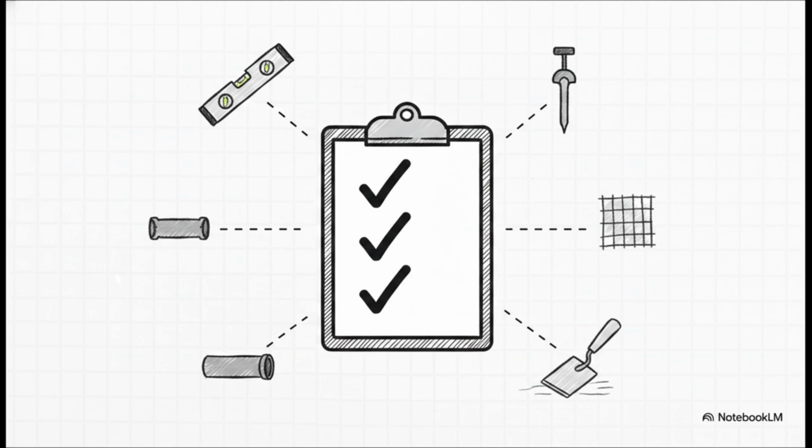Verify your chicken mesh is securely nailed at all the junctions. And finally, ensure the wall is thoroughly cured, pre-wetted, and spotlessly clean. Only after documenting these specific approvals should you ever sign the clearance for the plastering agency to begin.